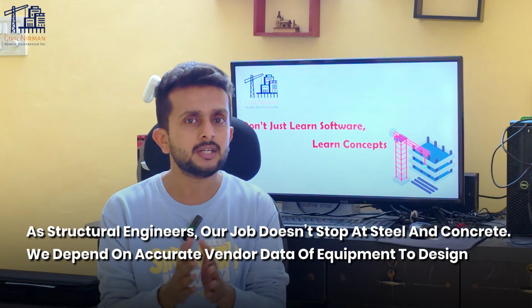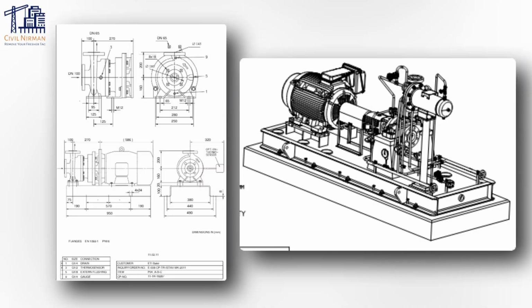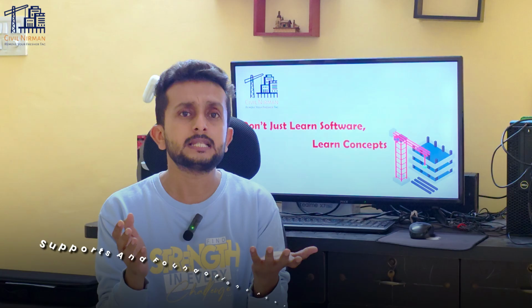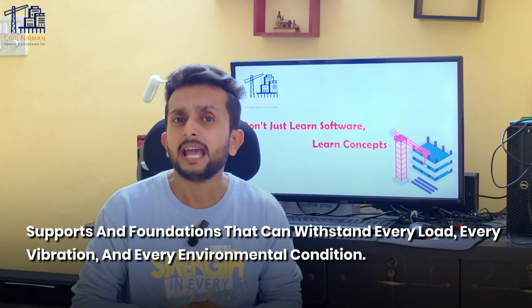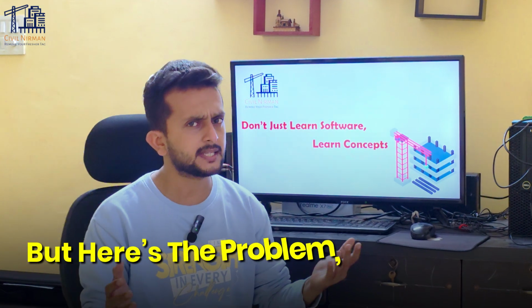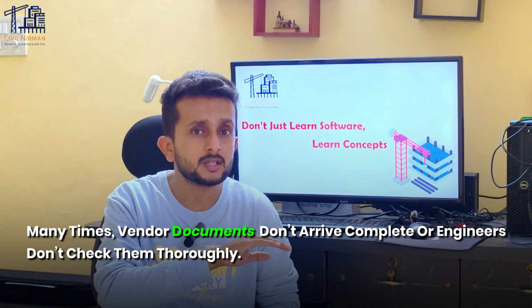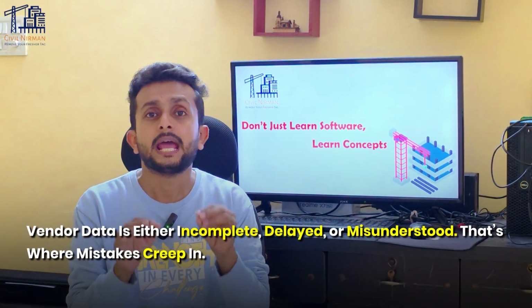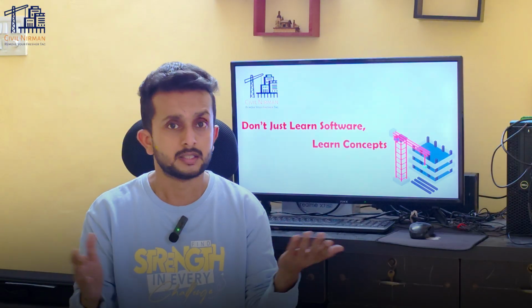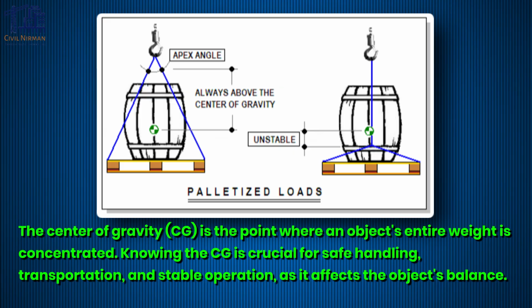As structural engineers, our job doesn't stop at steel and concrete. We depend on accurate vendor data of equipment to design supports and foundations that can withstand every load, every vibration, and every environmental condition. But here is the problem. Many times vendor documents don't arrive complete or engineers don't check them thoroughly. Vendor data is either incomplete, delayed, or misunderstood, and that's where mistakes creep in. If you miss even a single piece of information, let's say the equipment center of gravity or nozzle loads, your entire foundation design could be wrong.